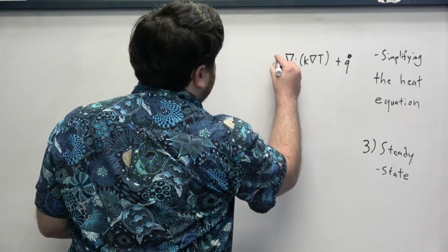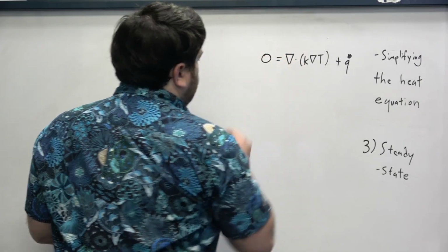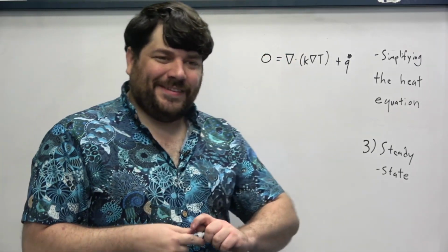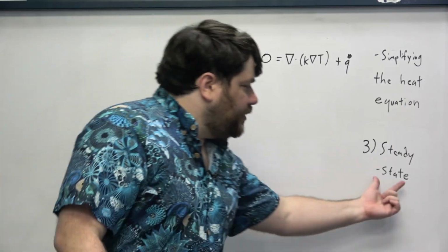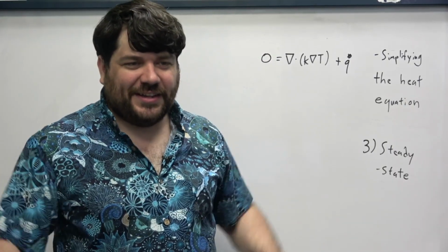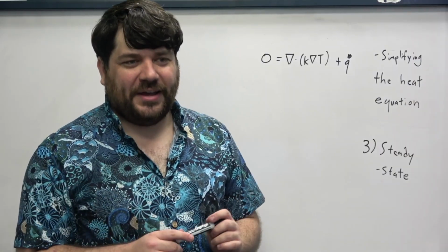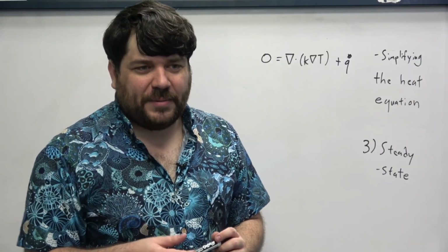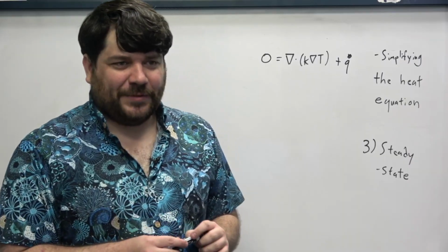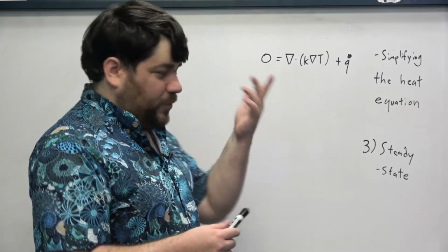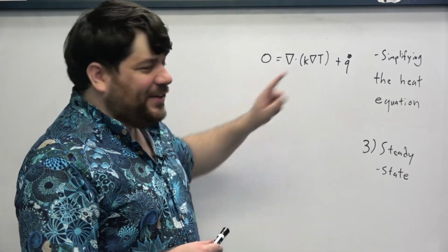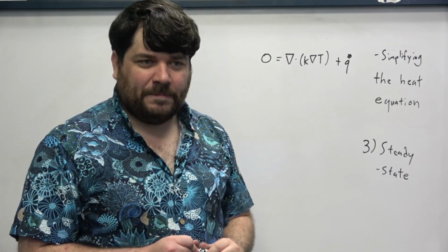This is kind of interesting, but perhaps not super surprising, because what this is saying is that if we assume that the system is operating in steady state, specific heat capacities don't matter. Densities don't matter. The only material property that comes into play when trying to solve the heat equation, or this simplified form of it, is the thermal conductivity.